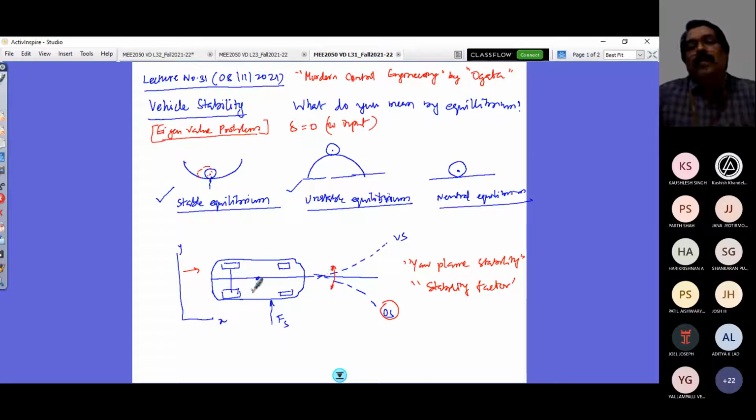If it is an oversteered vehicle, because of drifting that can take place, or the yaw couple which is created clockwise, it would make the vehicle get into the disturbance, and at that time there is a chance that your vehicle goes into an unstable state, and it may not come back to the straight path. That means the driver cannot exercise his steering easily, and that is dictated by a particular speed called the critical speed. So that's what you have seen. The critical speed is given by 1 by minus K3, where K3 is what we call the stability factor.